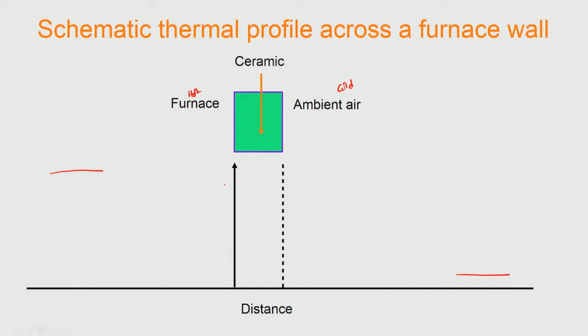So, these curves should come in, and we know that the temperature of the wall of the furnace is not the same as the temperature of the furnace. If the peak temperature is here, the wall temperature is somewhat here, and therefore we should draw it like that. Okay. So, Ts, the surface temperature, would be something like that, and we asymptotically take it to the peak temperature in the furnace. And this difference, Tp minus Ts, is what is driving the heat flux into the inner wall of the furnace, and outside also the same thing.